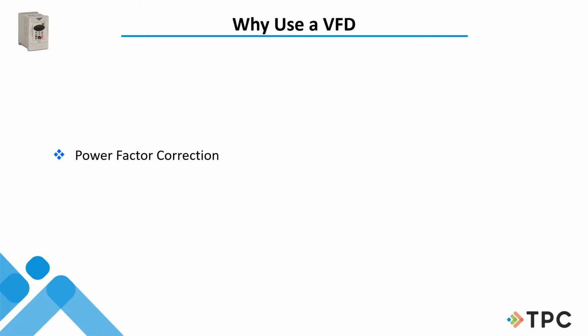They can help your power factor if you have problems within your facility. I would just tell you that before putting in multiple VFDs in any place, a power factor study of your facility is probably a good thing to have, to know what the frequency in there looks like, what disturbances are in there, because VFDs can create some disturbances in your internal grid.